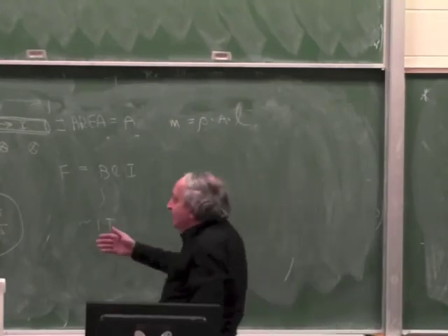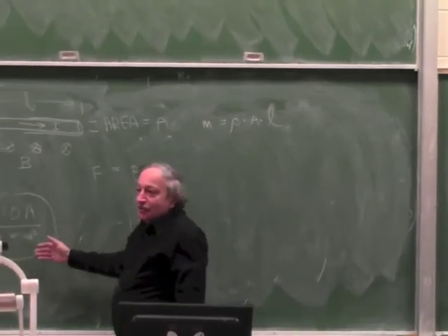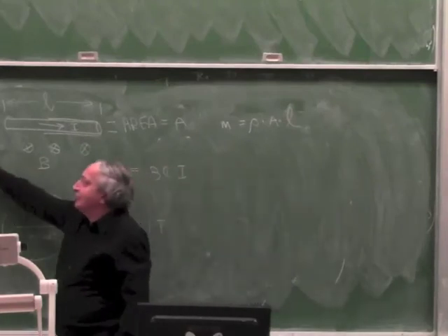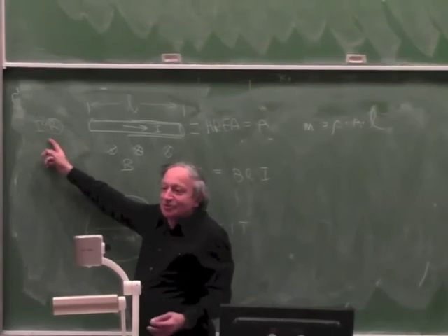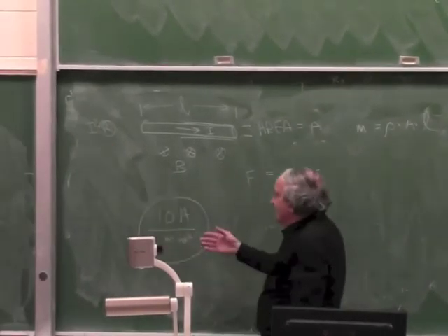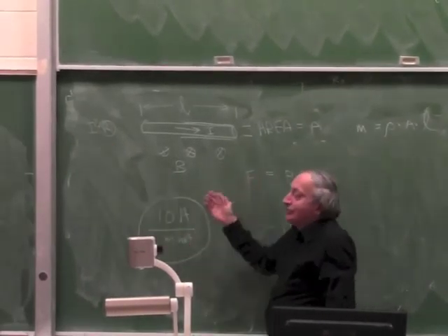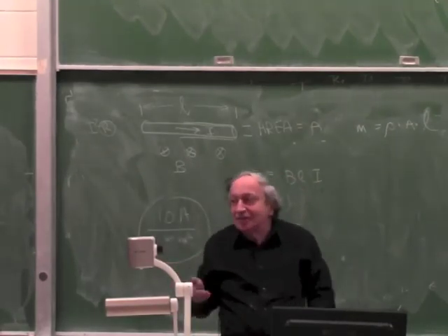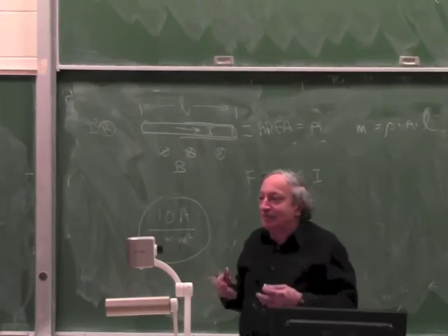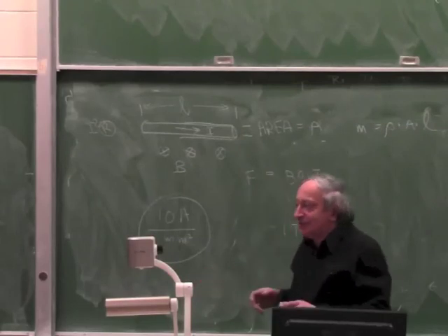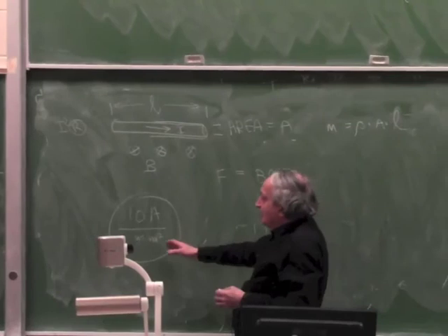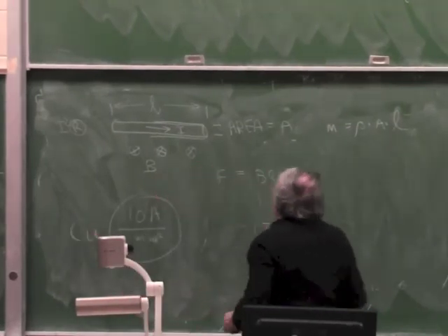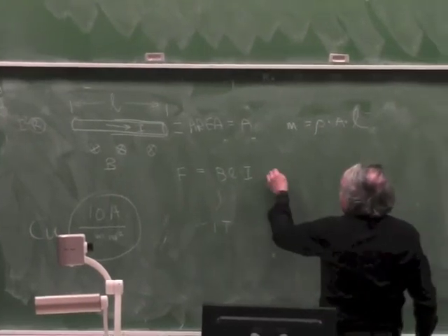Now if you run higher than that, the force will go up linearly with I, but the heat will go up like the square. So you pretty soon stop gaining. Say if you double this number, you'll only double the force, but have 4 times the heating. So instead of a 30 degree delta T, it'll go to 120 degrees above ambient, which is already pretty bad. So that's a good number to remember for copper. That's for copper. Okay, so this is roughly approximate.